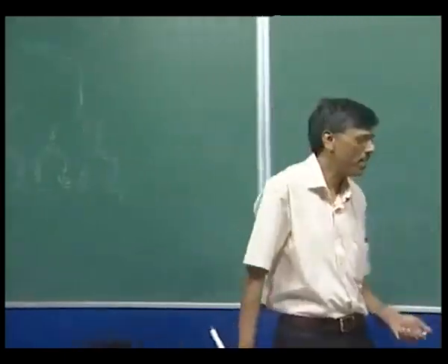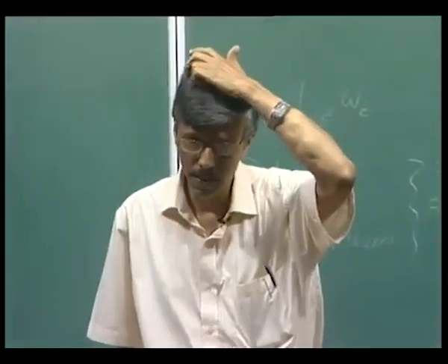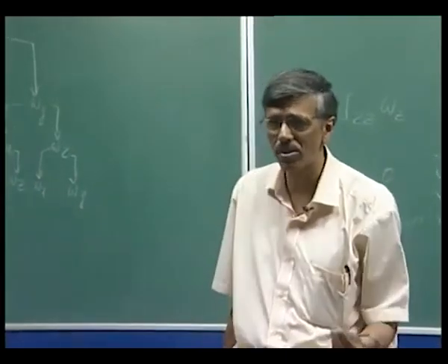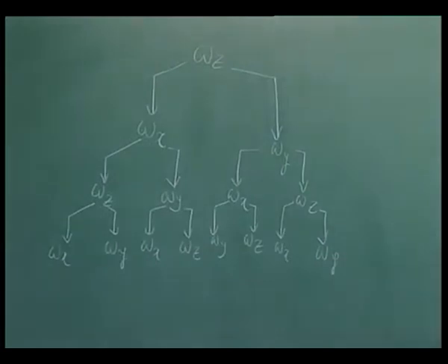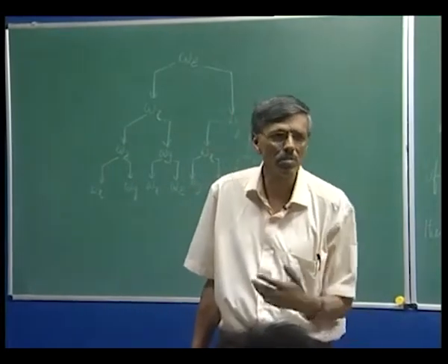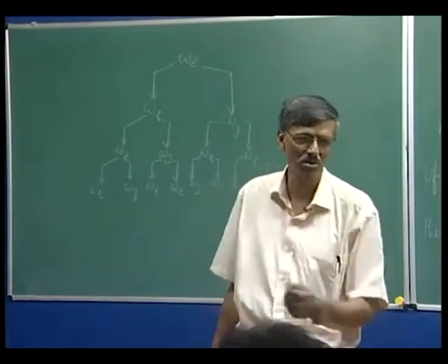This isotropic behavior of vortex stretching is also used in turbulence modeling when one does large eddy simulation. There, if you are looking at the vorticity at the smaller scales, they are going to be as isotropic as indicated here. And if this is not resolved in your computation, then you can model it, because now you are armed with the additional information that this is isotropic.